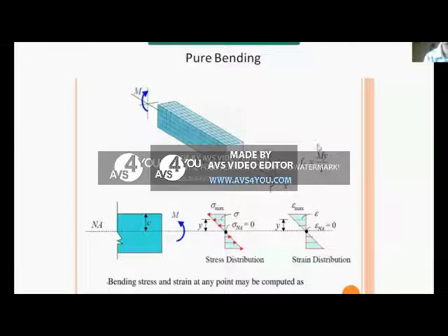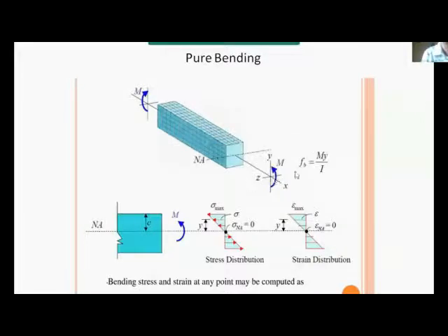of simple bending, sigma is equal to M by I into y. A famous flexure formula or bending formula, which is M by I equal to sigma by y, or sigma by y is equal to E by R. This we have calculated. Now, if it is about the vertical axis, then what is there here? M is the bending moment acting about the z-axis, and I is the moment of inertia about the z-axis, about which the moment is acting, and y is the distance from the z-axis.